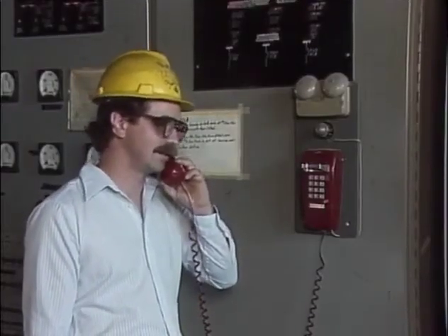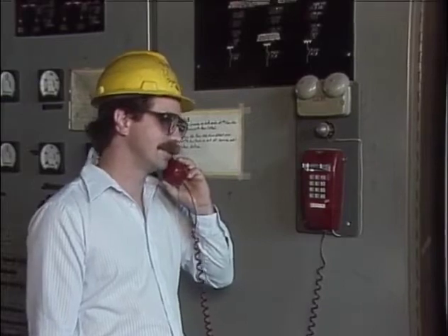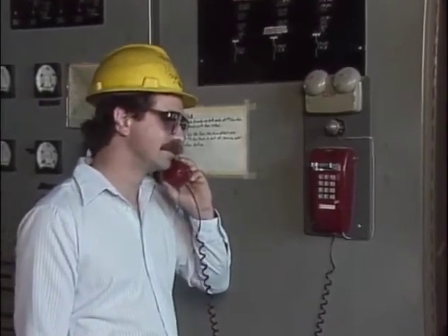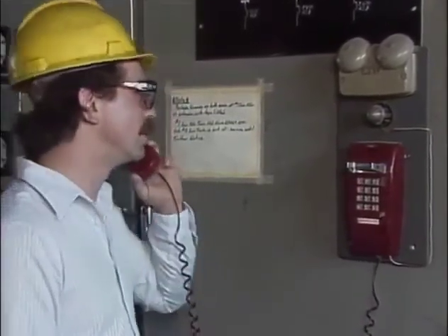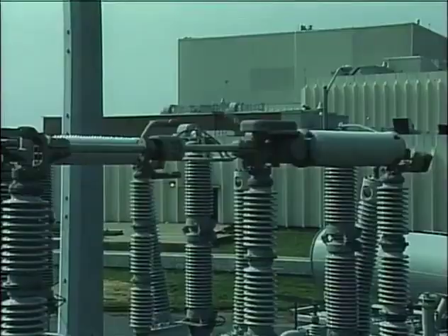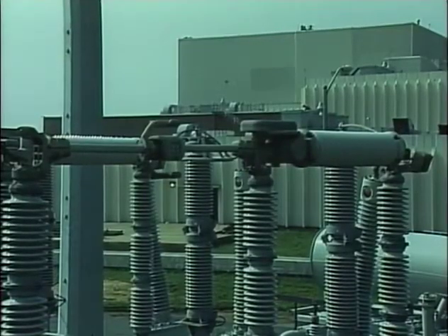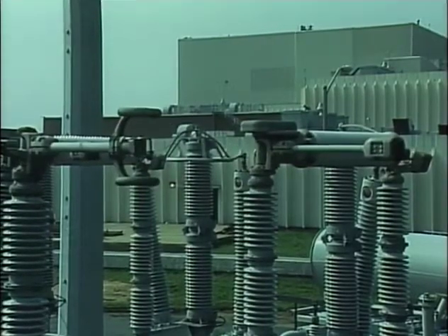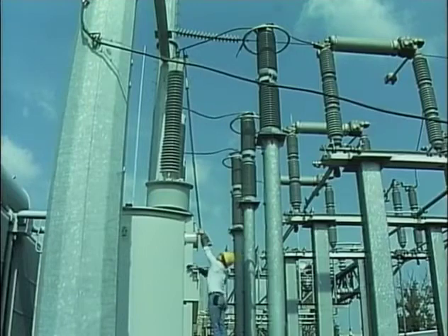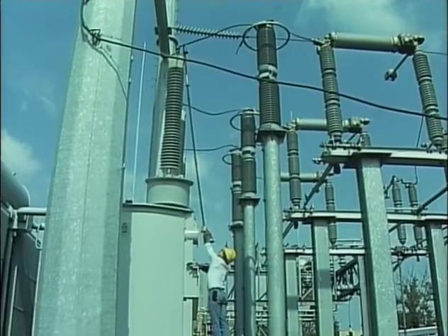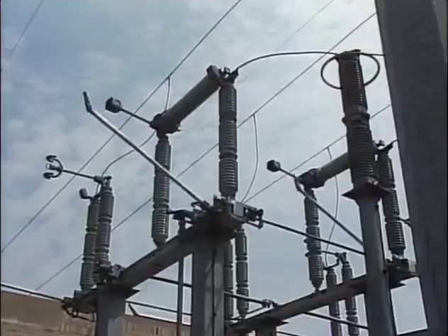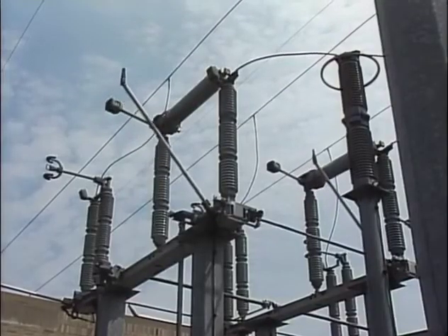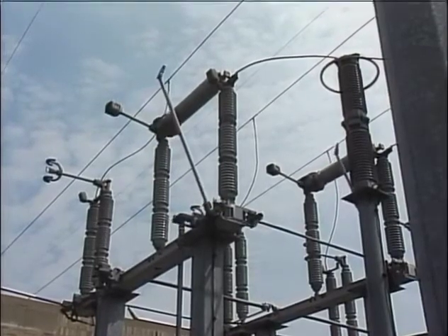The principles of taking a reactor out of service are the same as for clearing and grounding any other device in a substation. Permission and specific instructions are obtained for de-energizing the reactor and isolating it from the circuit. Here, an oil-insulated reactor is both de-energized and isolated by opening a motor-operated switch. After the reactor has been properly de-energized and isolated, it is tested for dead. Finally, it is grounded. Here, the shunt reactor is grounded by closing a set of ground switches.